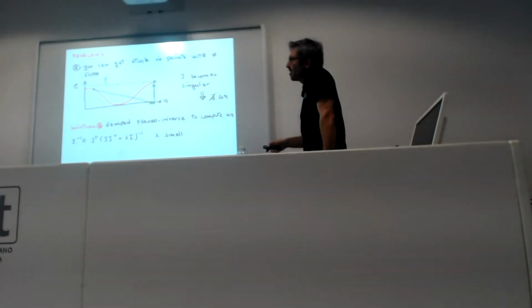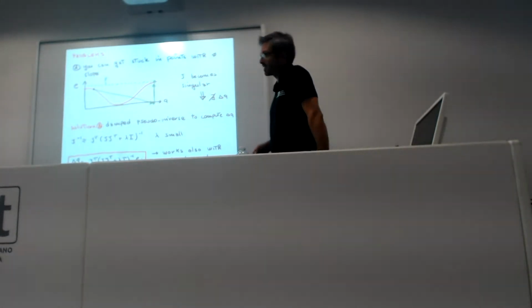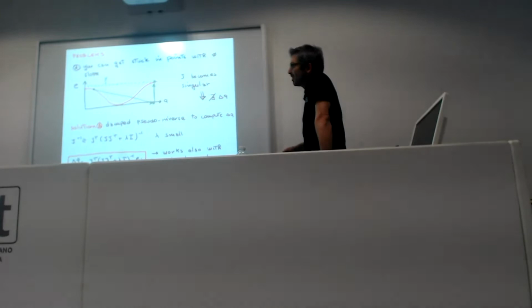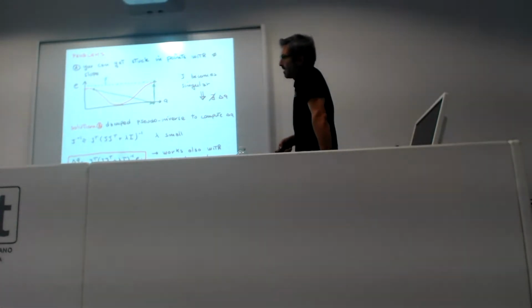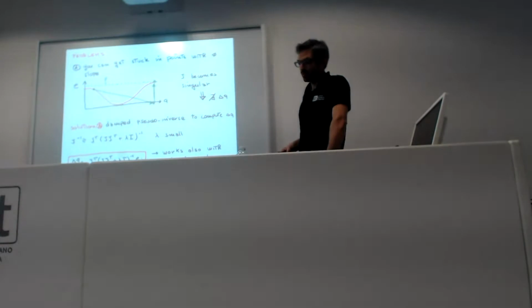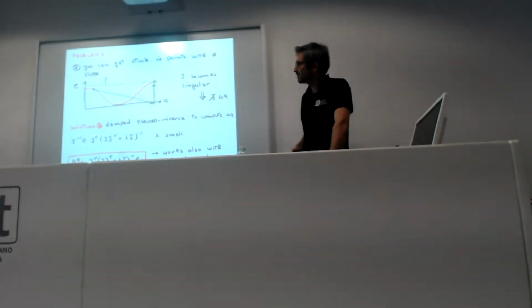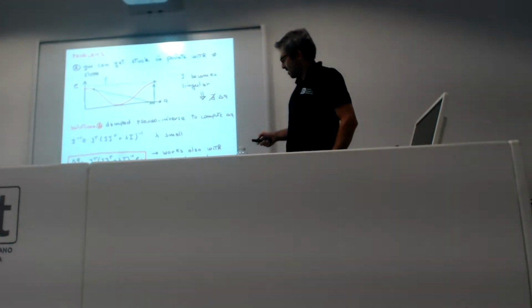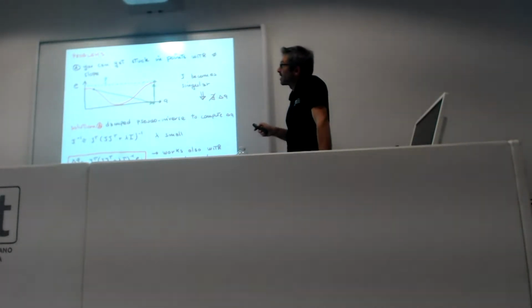This damping term ensures that a solution always exists, and the fact that this is a pseudo-inverse ensures that, as we will see in a later lecture, this approach works also for redundant robots, whenever you have more degrees of freedom than the dimension of your task space. And this is the update equation that is robust to this kind of problem.